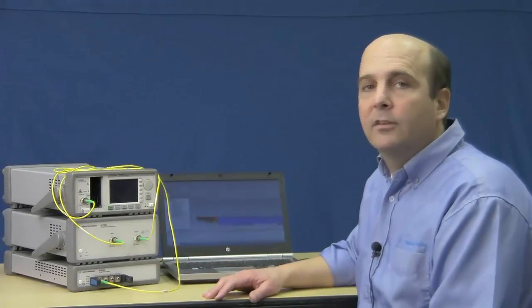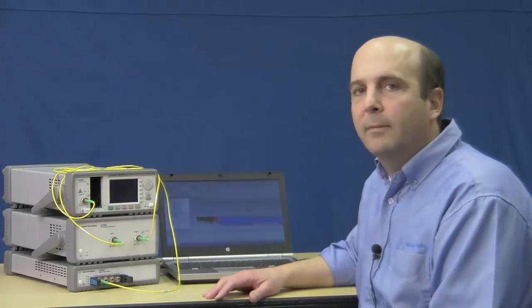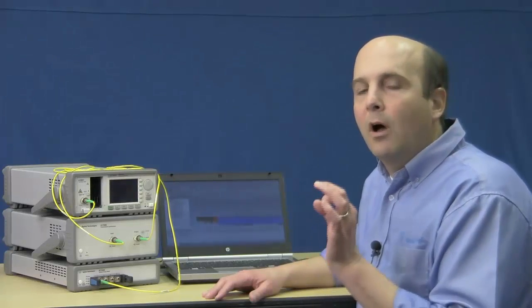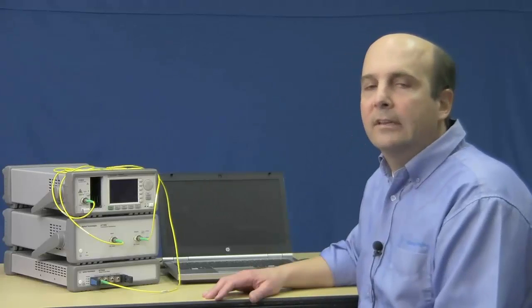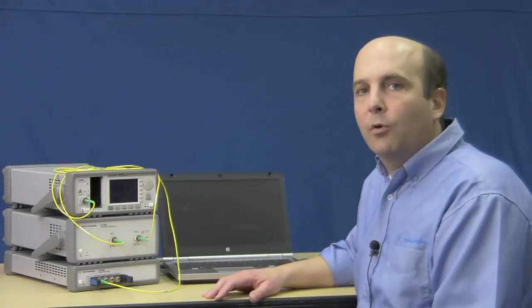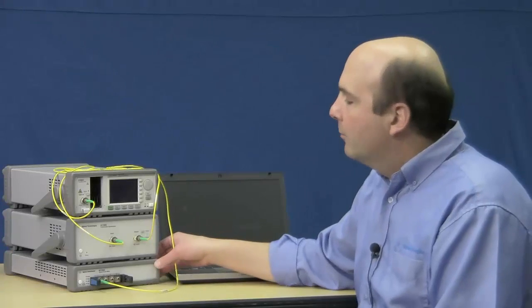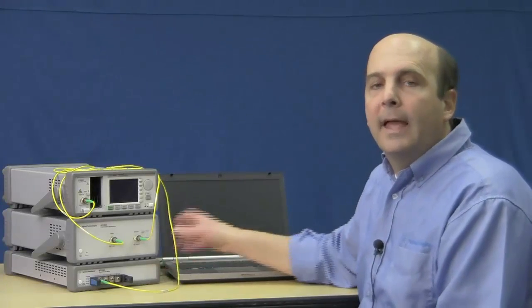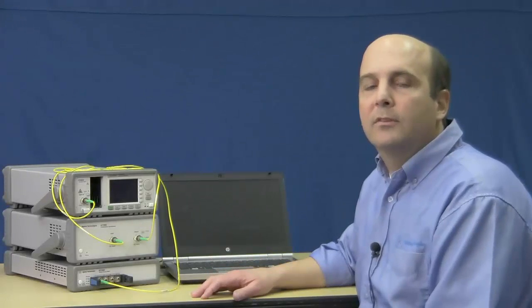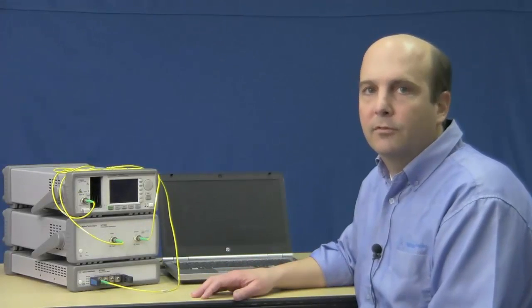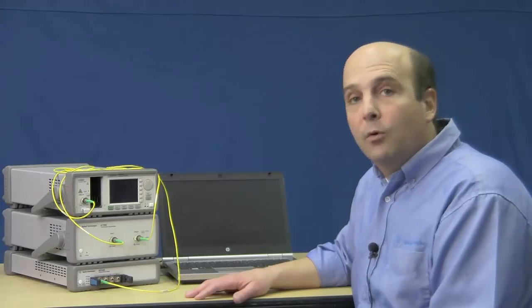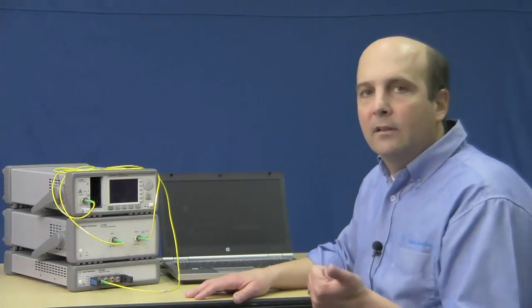And one of the main benefits of the solution for insertion loss and polarization dependent loss measurements is that it can do all of the required tasks in a single sweep. So during the course of the sweep, the polarization synthesizer quickly rotates the state of polarization while the power meter is measuring the power, and then we're able to perform the calculations once the measurements are complete using the Mueller matrix approach.